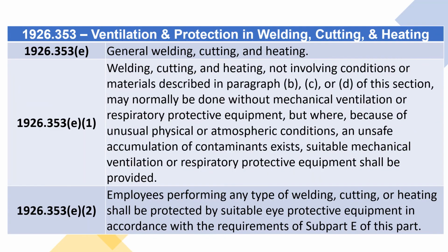E. General welding, cutting, and heating. E.1. Welding, cutting, and heating, not involving conditions or materials described in paragraph B, C, or D of this section, may normally be done without mechanical ventilation or respiratory protective equipment, but where, because of unusual physical or atmospheric conditions, an unsafe accumulation of contaminants exists, suitable mechanical ventilation or respiratory protective equipment shall be provided. E.2. Employees performing any type of welding, cutting, or heating shall be protected by suitable eye protective equipment in accordance with the requirements of Subpart E of this part.